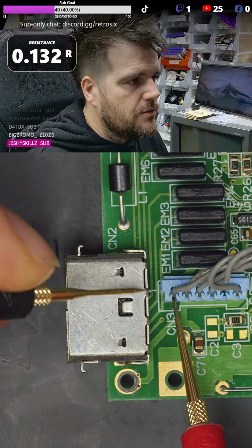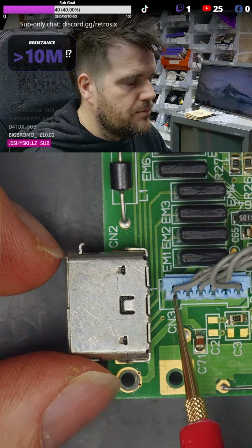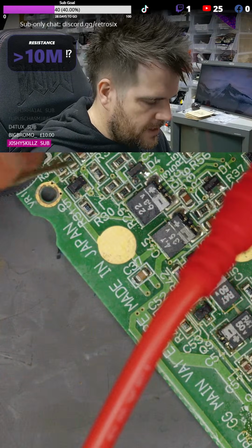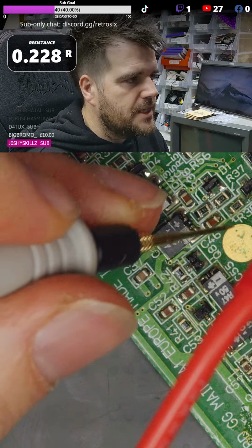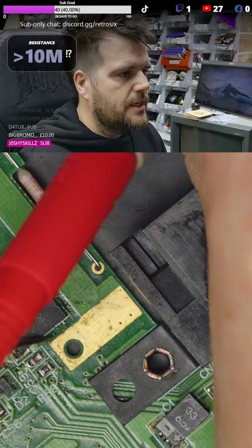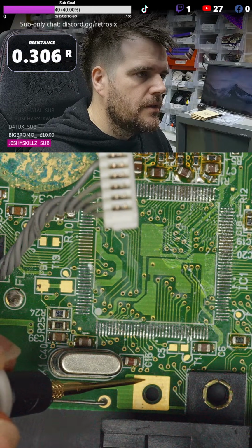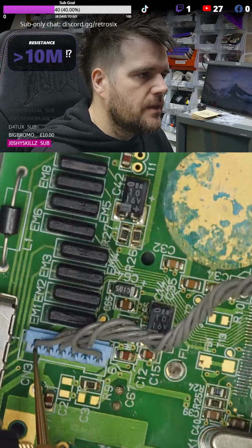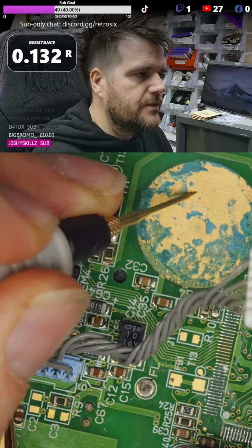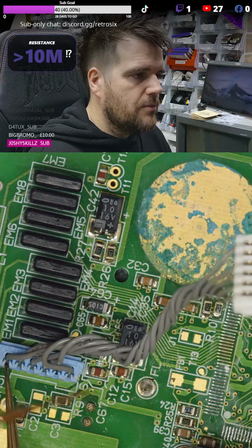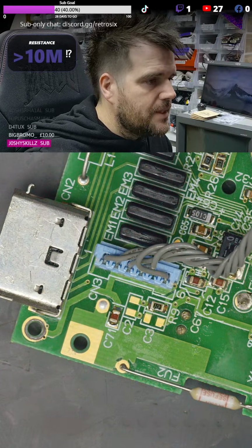So you know the fact that you're close to where this physical pad is here. Now, if I move the ground, leave this one probed here, and go to a ground point over here, say, look how it's changed. So I can use this as almost like a location detector. We get closer, and it starts to get a bit less. We go over to this ground, that's actually more there. That ground is obviously the low one. This ground's low. So once you start getting close to the ground point, using the super low ohm reading, you can try to narrow down that a bit more.